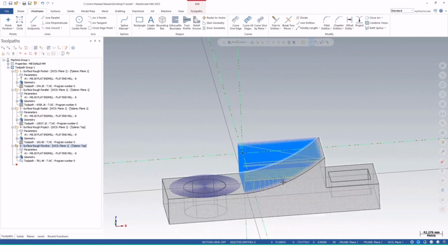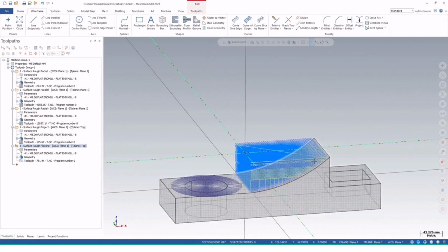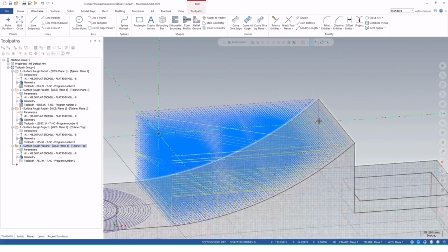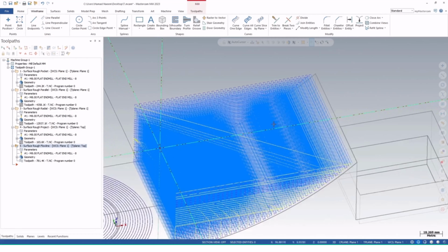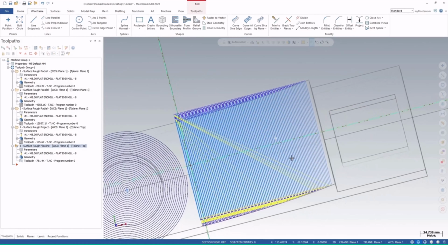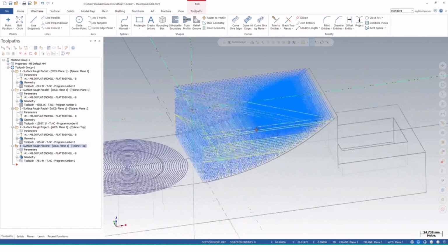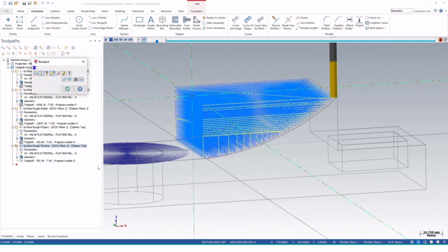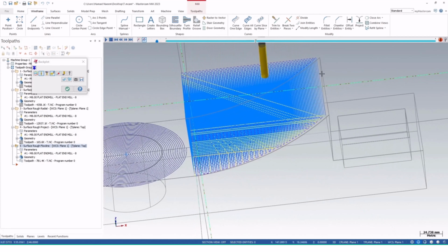The finishing operation will be done in the previous tool. Okay. So this is how we can perform the roughing operation by 2 millimeter step over. Okay. So let me show you how it will work like that. This is how it works, and it removes the material from this side. This is 2 millimeter step over. Okay. So each tool path is 2 millimeter forward.